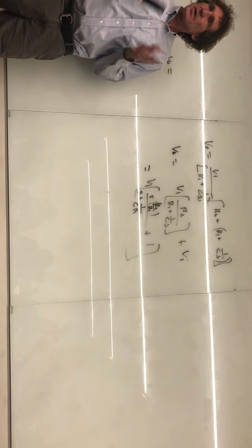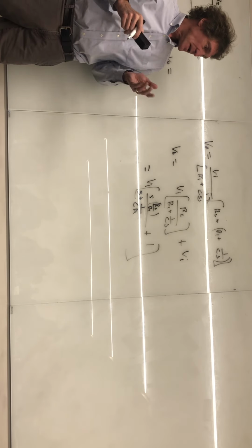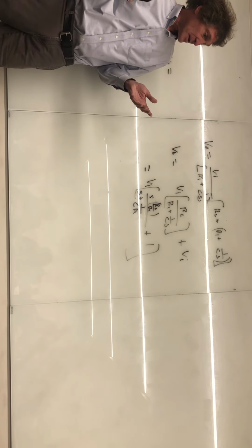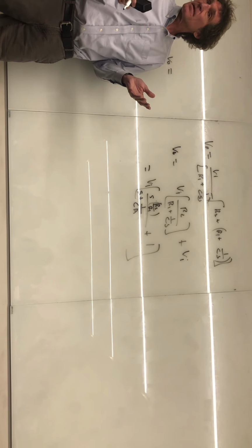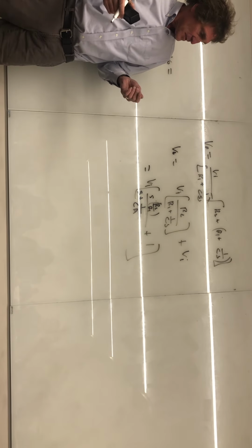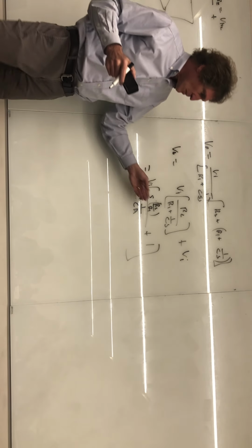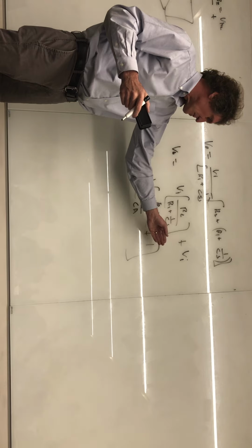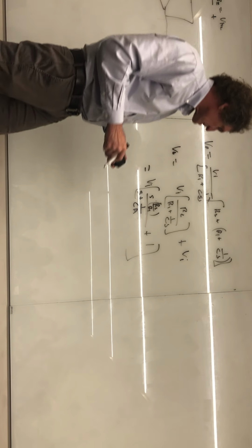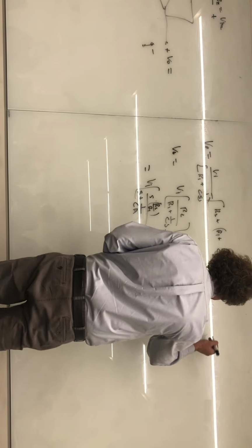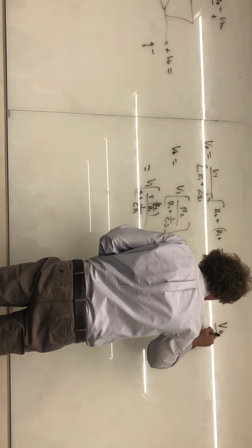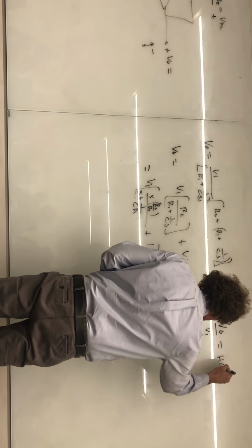Here I'm just trying to manage things, make them a little neater. Now I don't have to get a common denominator, but I'm gonna for the heck of it. So if I do that, and I multiply 1 by S plus 1 over R C1, downstairs is S plus 1 over R C1, now I get V out over V in is my transfer function.